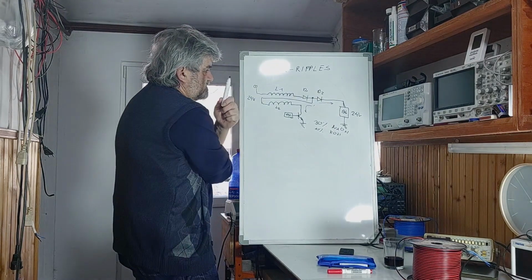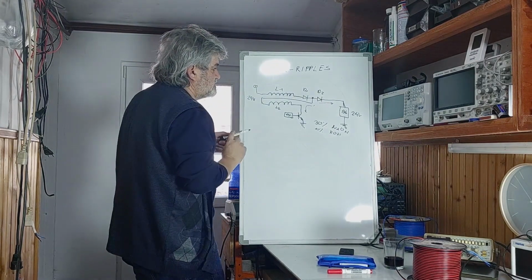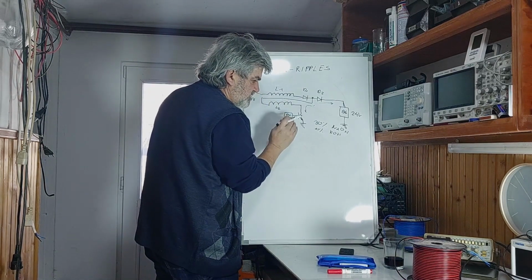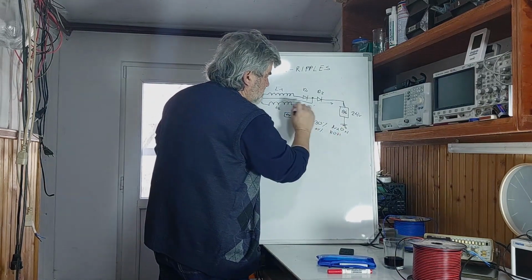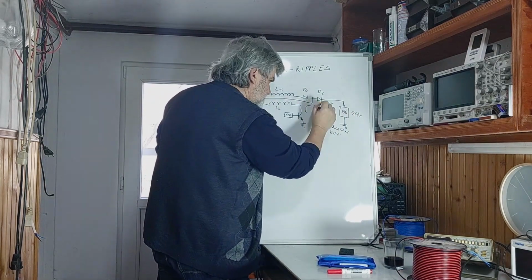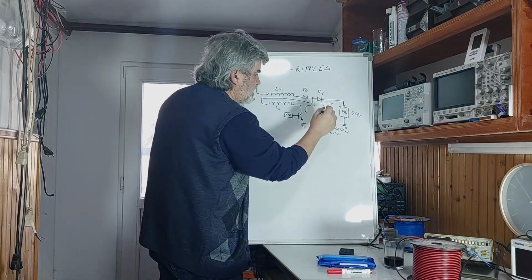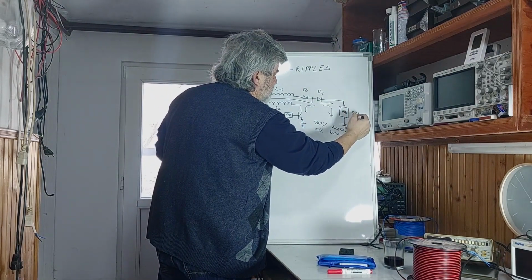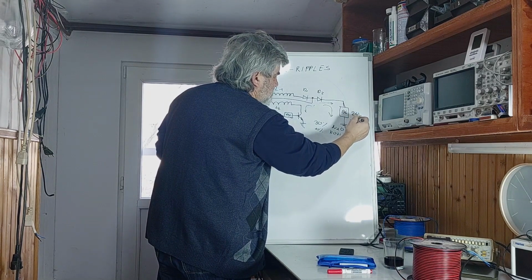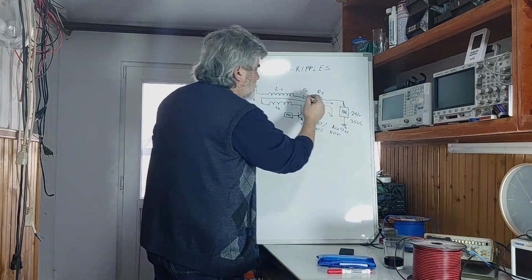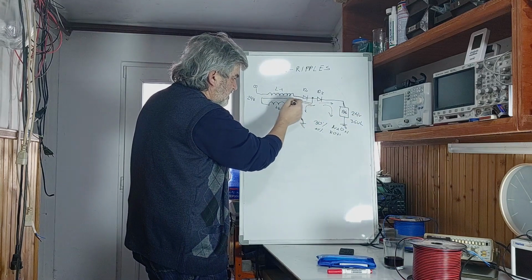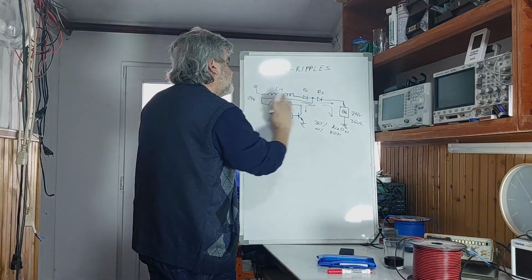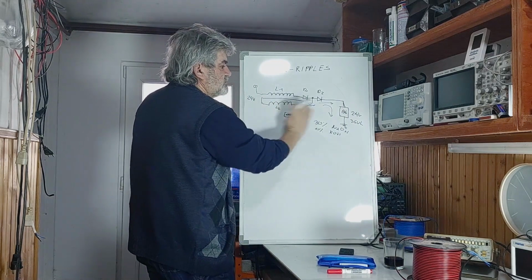What I also notice is that it doesn't work well like a buck converter or booster. If I go to 12 volts, it's not good because high current will go there. If it is boost, which means I go to a 36 volt electrolyzer, then higher current will go here, so it will not be efficient like when it goes one-to-one, so to speak.